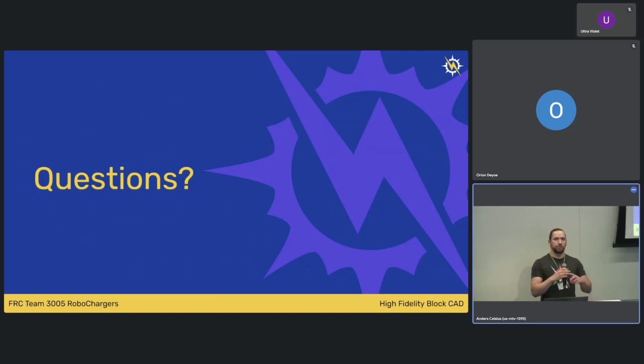I do a lot of triangulating out things and then using equals constraints to make the triangles the same size, to make mechanisms in multiple positions have the same geometry, even with only 1 dimension. I really don't like having the same dimension on a part that's representing the same part in multiple positions, because if I change it once and forget to change the other, then my layout sketch is invalid. So I'll use a lot of construction geometry to tie that stuff together, and that's what those dotted lines are.